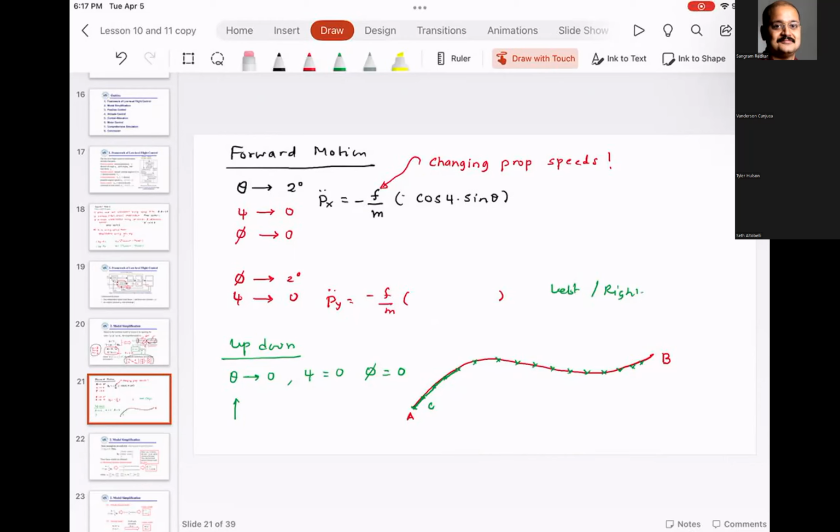Now, clearly, when you have an ultrasonic sensor, it actually detects based on the reflected wave. So if you have maybe a desk, or some type of an obstacle, and if your quadcopter flies over that obstacle, the momentary value of Z will be different. So you should be trusting your pressure sensor values more.